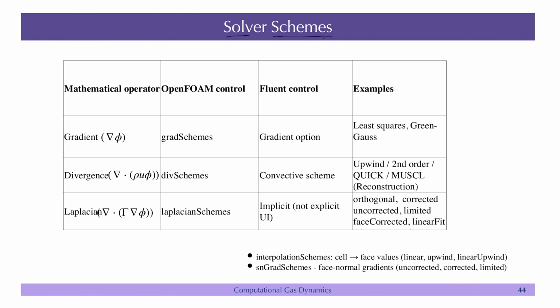One thing is the flux scheme that you choose, but as I mentioned earlier, OpenFOAM does not have many flux scheme based solvers, because it is primarily a pressure based solver. So, we will look at some of the schemes used for the gradient and reconstruction. Both are finite volume based solvers. OpenFOAM and Fluent both are finite volume based solvers. You can use unstructured grids for both of these.